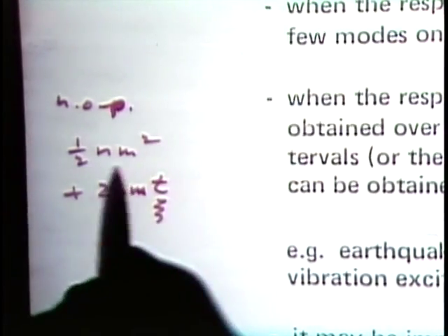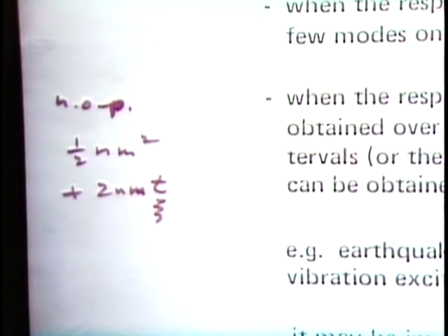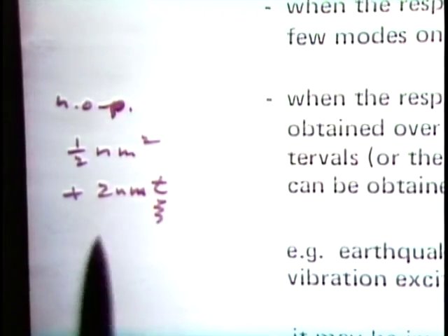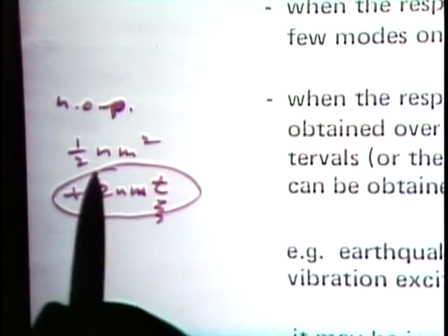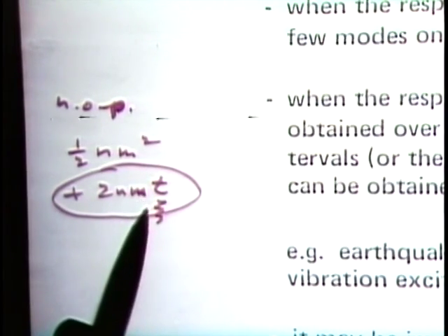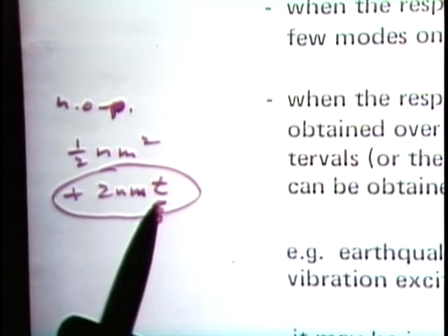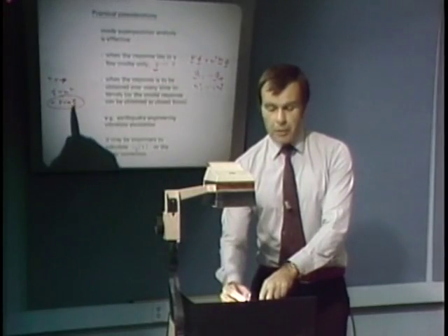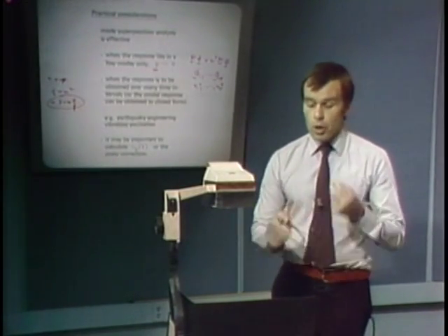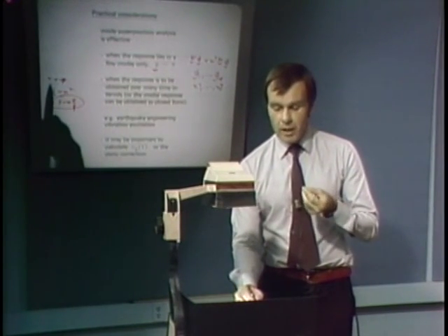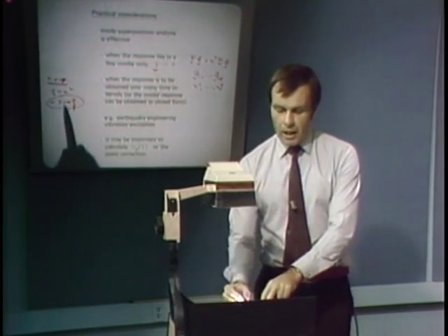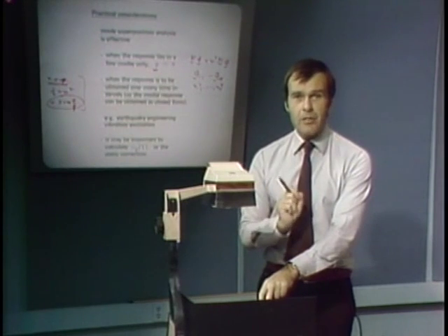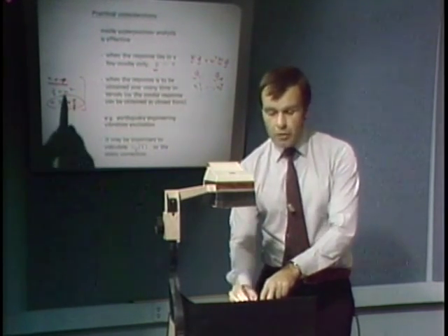This is an initial expense that we have to perform using the direct integration Newmark method, for example. The same holds for the Wilson theta method or the Houbolt method. This is an initial expense, and then we perform this number of operations for each time step. Now, if we have to run 5,000 time steps, then direct integration would be extremely, extremely expensive. In fact, you might not be able to afford it using implicit direct integration. Therefore, you can see directly by looking at this operation count, what should make the analysis more effective is to bring down the bandwidth.